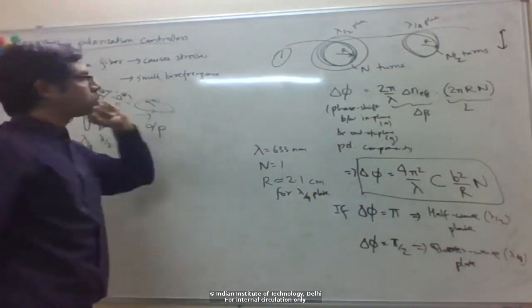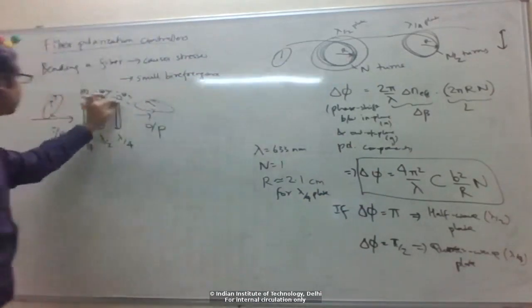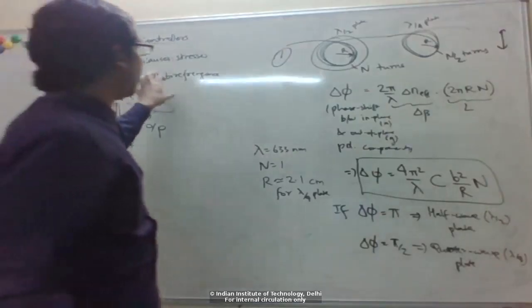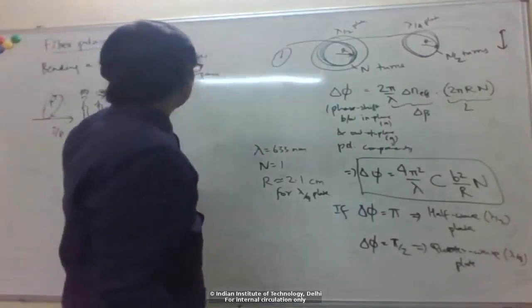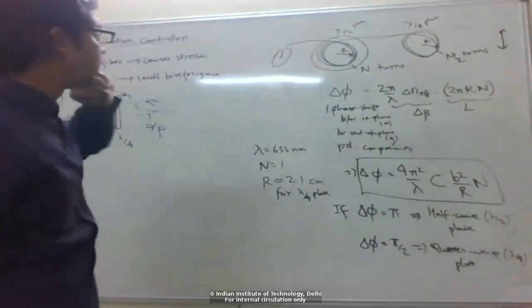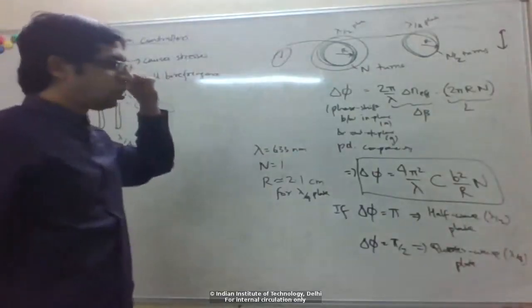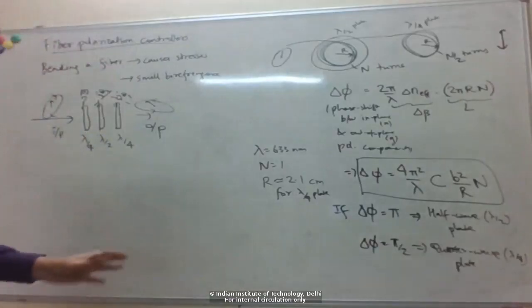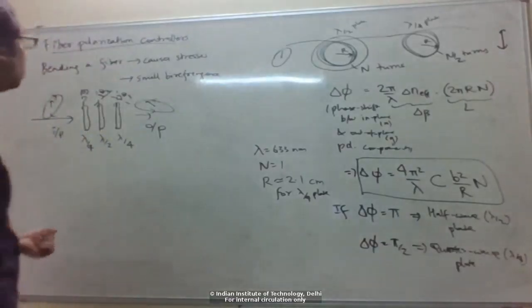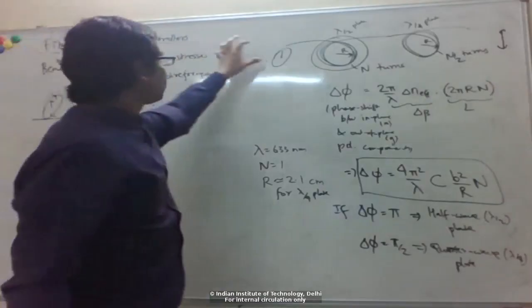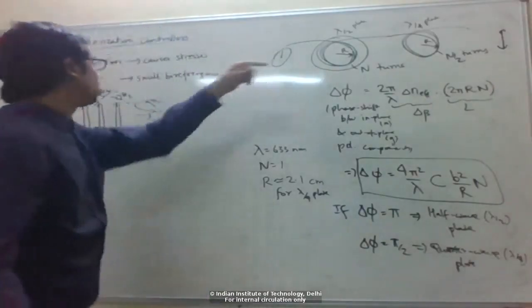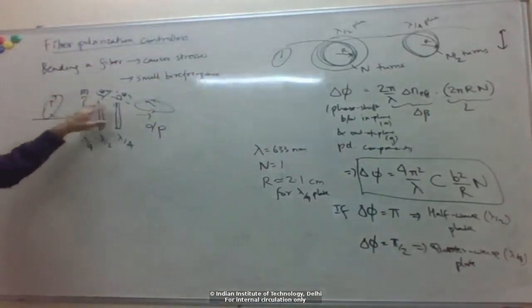Once you get the output polarization you want, you set these angles to that. Recall that as the polarization gets scrambled along the fiber, it's a static distortion, which means there is no time variation. Whatever scrambling is happening, the polarization here is fixed and not varying with time, so once you figure out what angles you need, you can just set it.